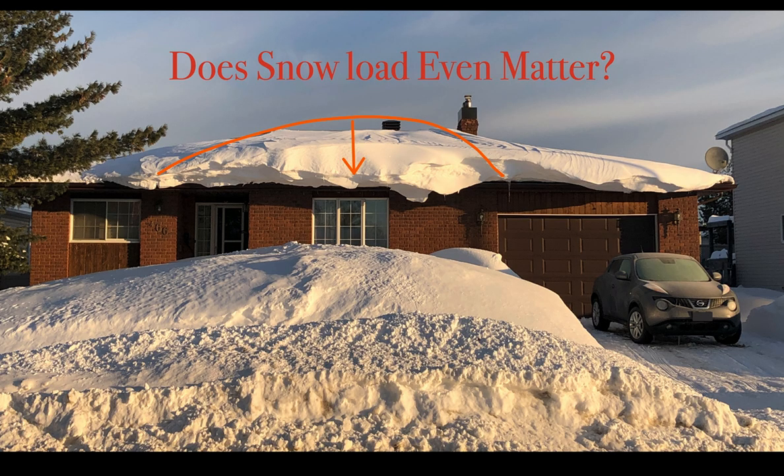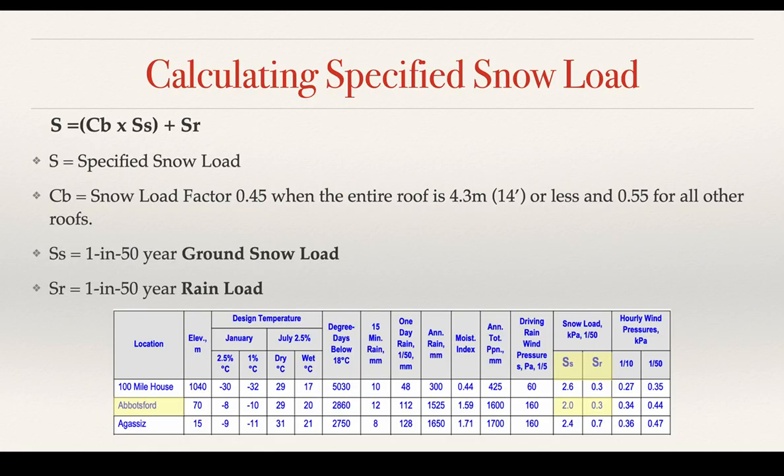You'd start seeing the effects of that on the structure. And even over here, if you look at the snow buildup on this side, pressing down on top of that garage door, that's going to be a lot of weight as well. So, of course, the snow load factor matters. Now, this is light, dry, fluffy snow, but if it got rained on, that would just increase. So we need to basically prepare for the worst case scenarios.